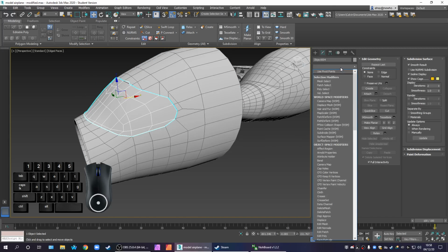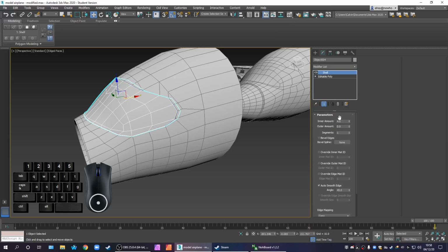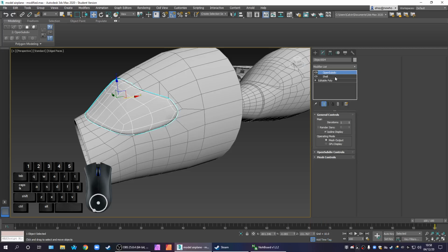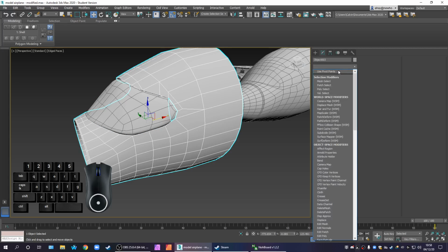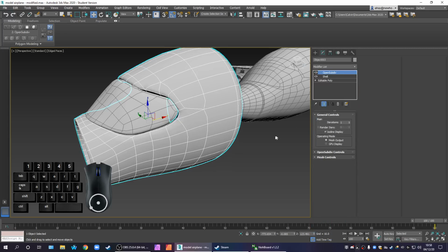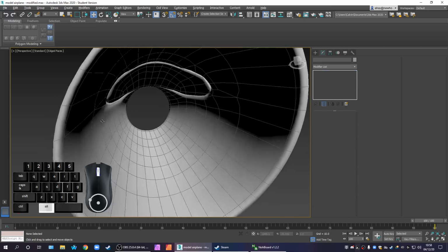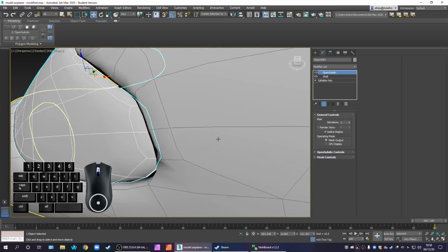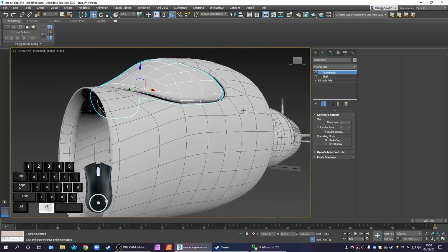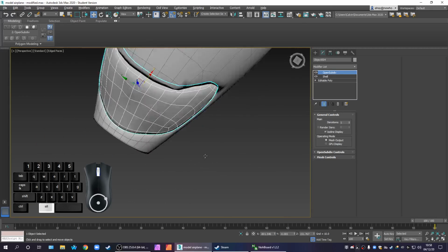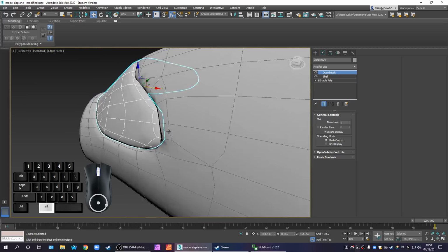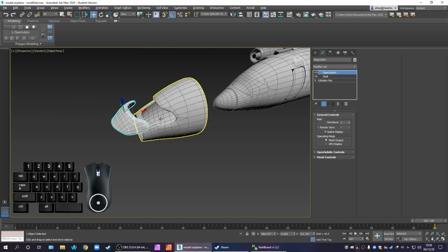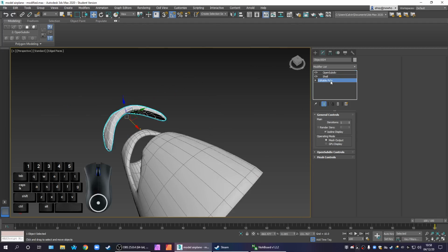If we put the same shell on here, and then we do our open subdiv, curves might be closer. And again, the precision of the printer is not so good, so I really ought not to be aiming for some kind of crazy tongue and groove fit. I ought to be aiming for the kid's going to sand it a little bit and then it'll kind of slap in there, right?